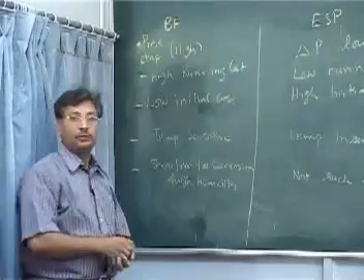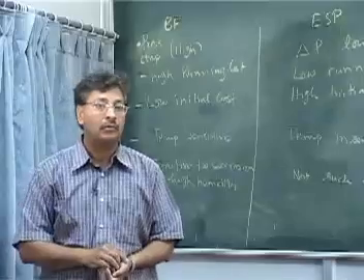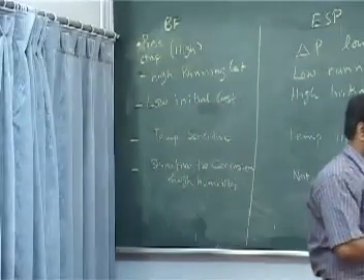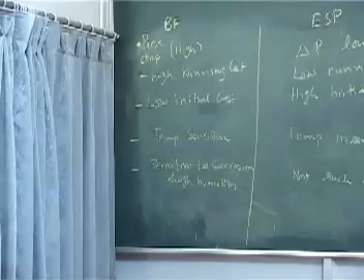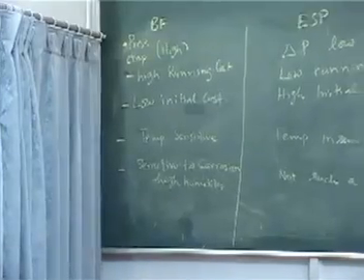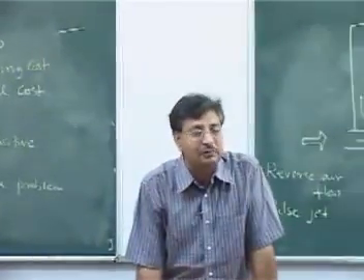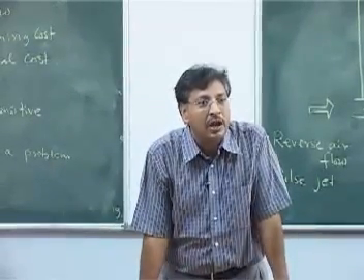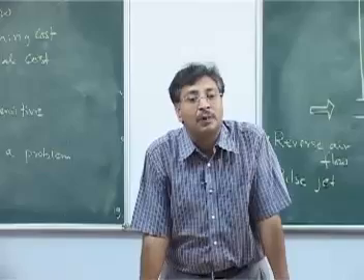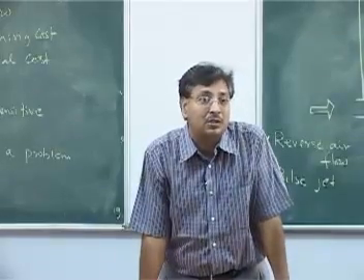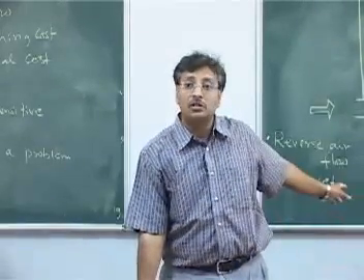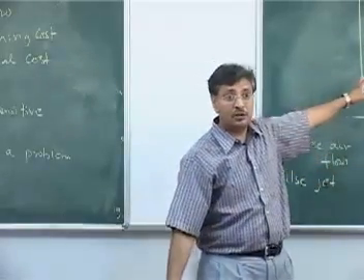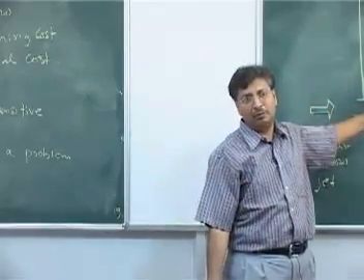Then one more thing is the running cost in the case of ESP. There also we can consider it high because of the power requirements. Comparatively, again we are not giving the numbers, the question is well taken, but the cost of running this one is not so high, depending on the power plant you are dealing with. That cost is very small, but here the cost of blowers and the pressure drop is really very high.